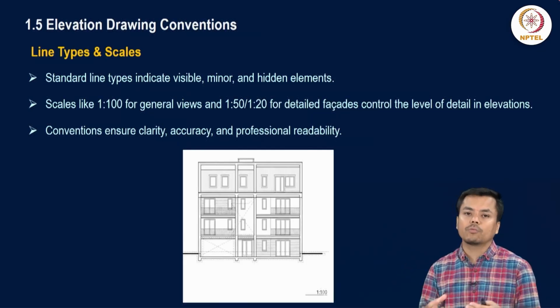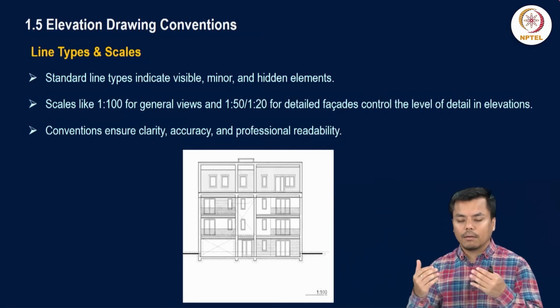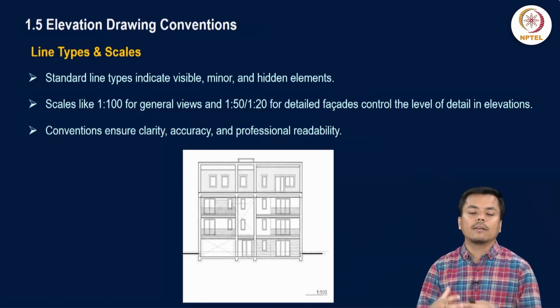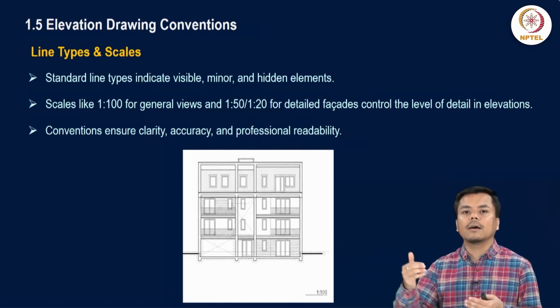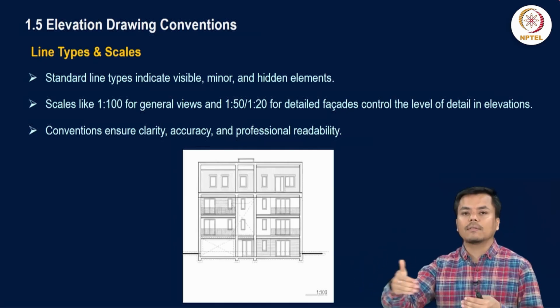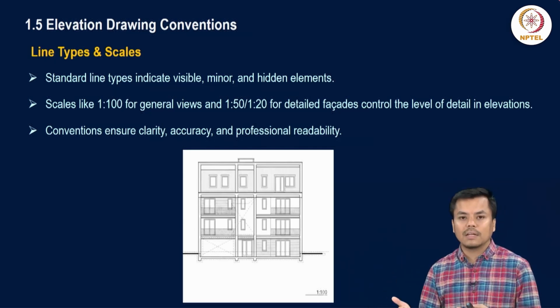So that is what has to be represented in your elevation also. So using bold lines or increasing the line weight, your facade has to be designed in that way. If there is any projection, that has to be showcased with thicker lines than the elements that are in the foreground. Likewise, the intensity of line has to vary, and the line type will also indicate the same story.